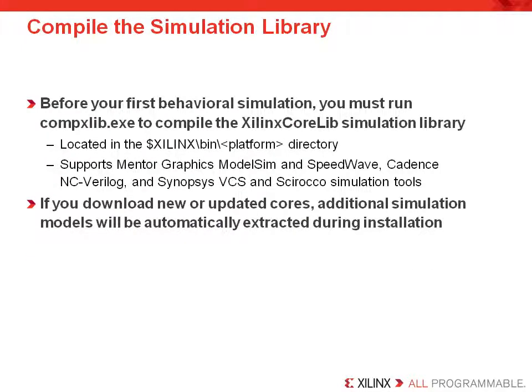As I mentioned earlier, you will have to compile the simulation library when you install updated ISE software. However, if all you do is upload some new cores, you won't have to compile the behavioral simulation libraries again. Please note, many VHDL simulators require low-level files to be analyzed before the file that references them.